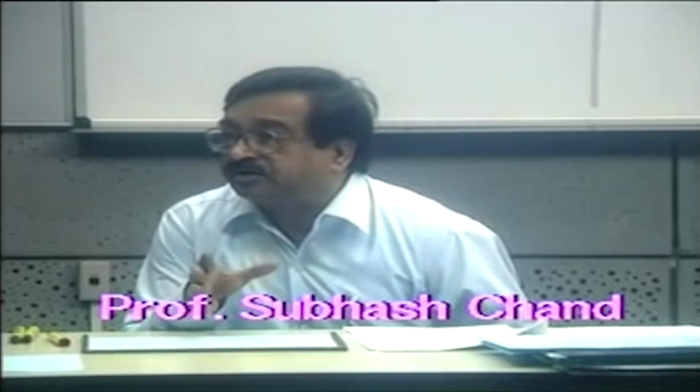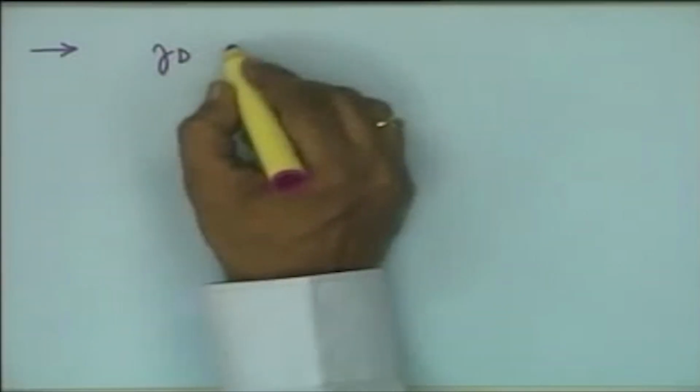Another approach now, so basically what we are looking at, a general approach to understand the external film diffusion, is that we determine by some experimental method or an analytical method or an empirical equation the magnitude of the mass transfer coefficient, and the magnitude of the mass transfer coefficient will give you the magnitude of the concentration gradient. And so, another alternative route to estimation of the mass transfer coefficient has been on the basis of some empirical relationship, what we call the JD factor.